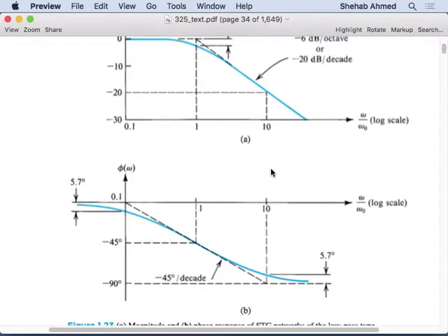And let's say in a speaker case, I don't think the phase shift is very important. I don't think somebody will recognize it, as audio signals are around 20 kilohertz. If there's a phase shift, 1 over 20 kilohertz is what? It's a very small amount of time. So if Abdulaziz is singing, for example, and I'm sampling that at 20 or 40 kilohertz, then my samples are very close to each other. Fine.